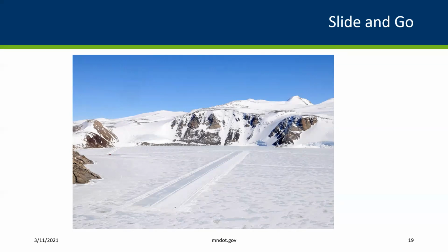When we touch down, we realize looking forward that it's a lot more of a glassy surface looking than just snow. I gently touch the brakes, and there's absolutely no braking action. So I immediately elect to not try to stop, because if we did, we probably would slide off the end. If we did stop, we wouldn't be able to legally take off. So we do a go around, we climb up out of there, and we divert to our alternate airport. Ultimately, everything worked out okay for us. We were able to maintain direction control with the flight controls on the airplane and divert safely.